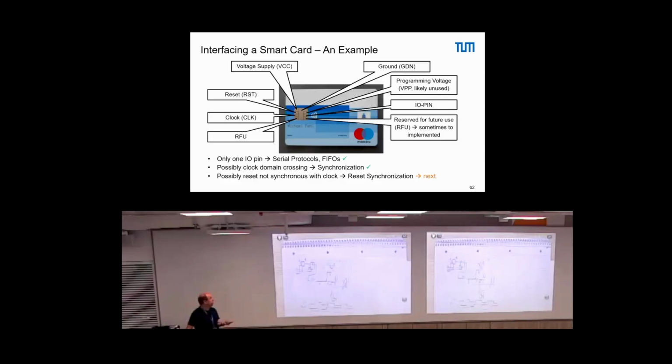So what we do is we combine the two and we build such a reset synchronizer. So why are there more than one flip-flops? Just as we can have with an input in a clock a root cause for a metastable state, we can have the same with a reset in the clock. So this is effectively why we want to have it. Good. Any open questions to this reset synchronization stuff?